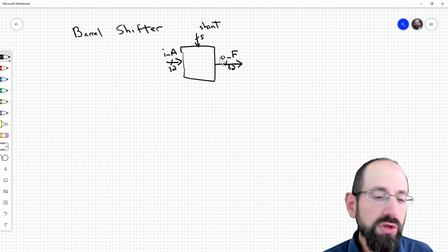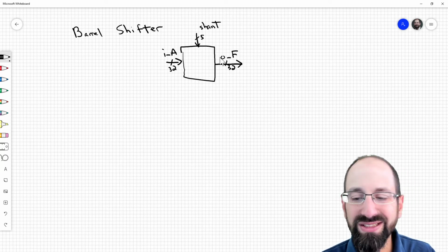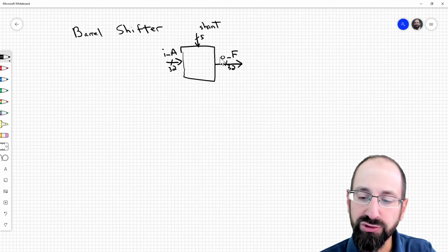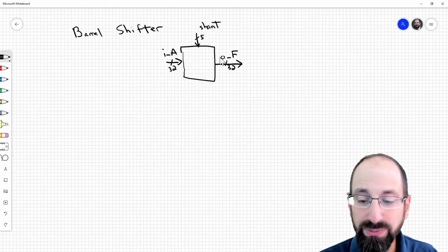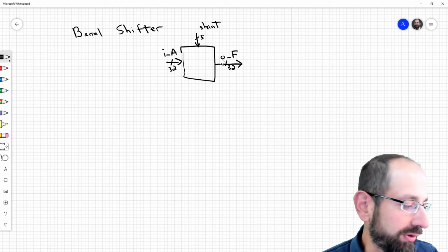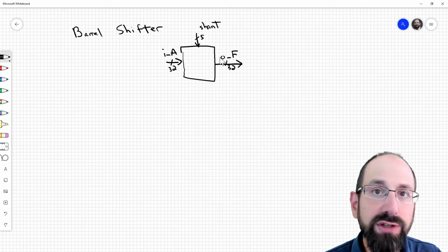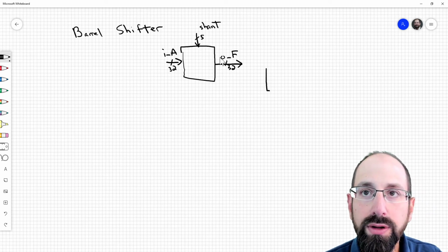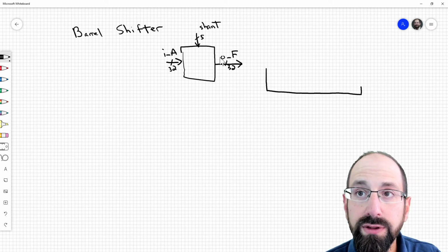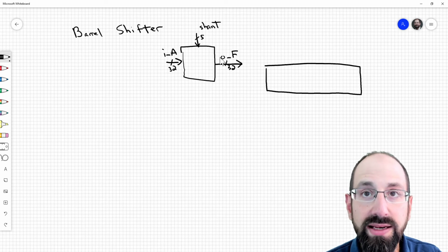My approach to the shifter is just to break it down bit by bit versus trying to implement it all at once. And that's what you get when you try to design a barrel shifter. In fact, we can look at that shift amount and break down the 5 bits of shift and treat them as independent of each other.